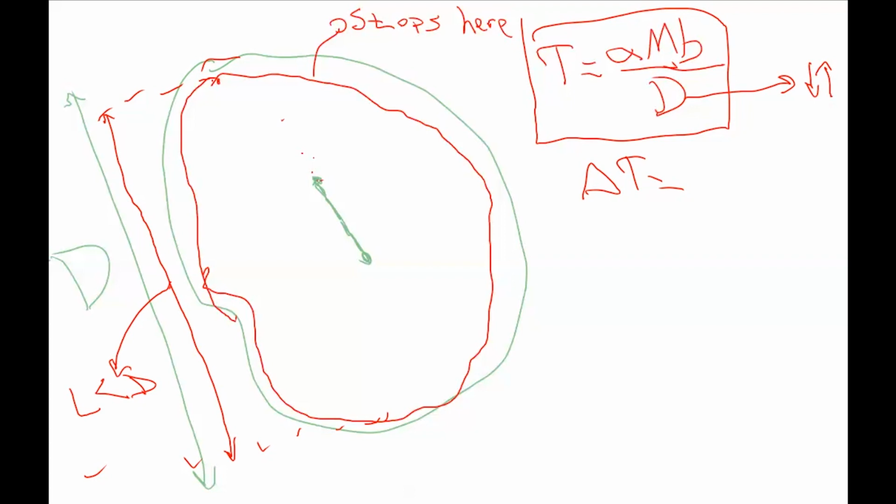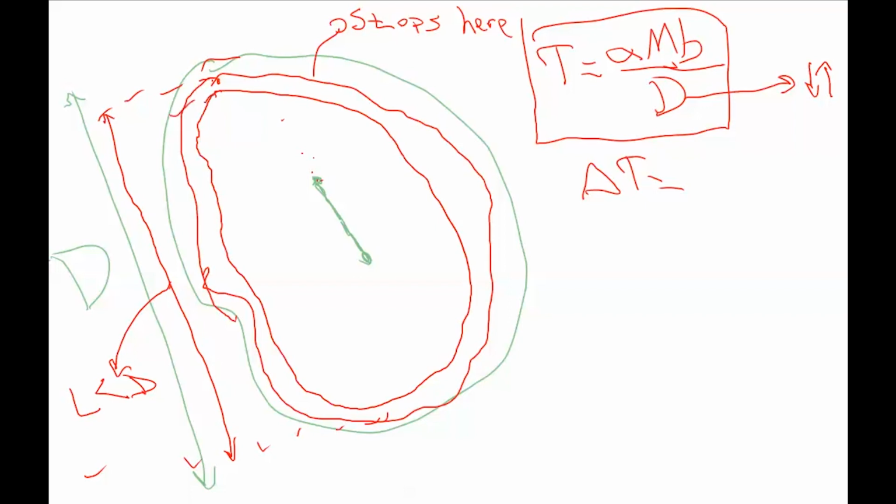Once we activate the second dislocation, it will hit and stay at this location. Then we will again need more shear stress to activate the third dislocation because this L, this time, is less than the previous L. Let's call it L1. Right?